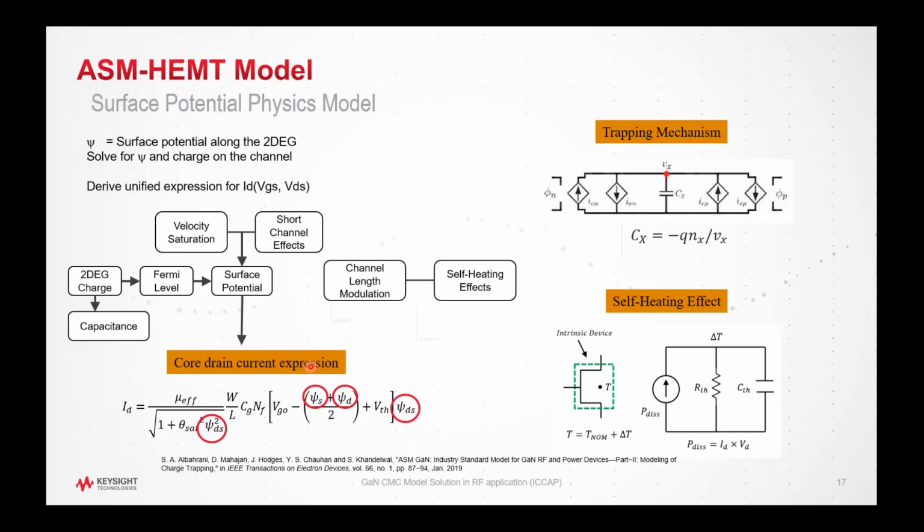So it puts all these equations into a unified form by solving the Poisson equations, by solving the surface potential equations. So that's why it looks like this. And it also has the trapping mechanism and self-heating mechanism all included in these equations.